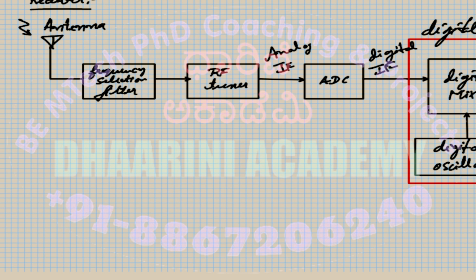On the software side, I will tell you another advantage. On the receiver side, you can perform what is called channel estimation. Channel estimation is very important in communication, because normally channels have a time-varying frequency response. Time varying in the sense that, say, during sunlight the nature of the channel is different, and as sunlight reduces or increases, the channel's property changes with respect to time.